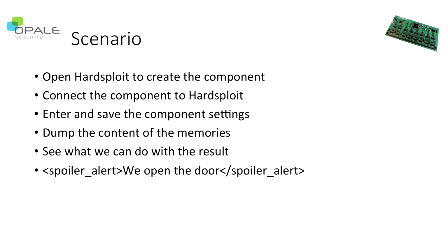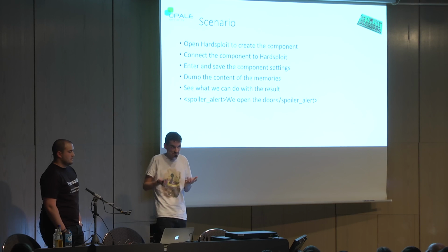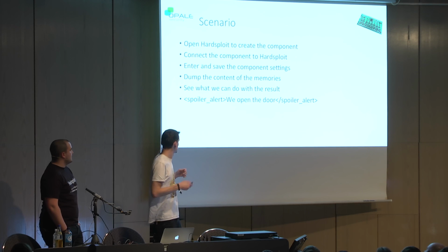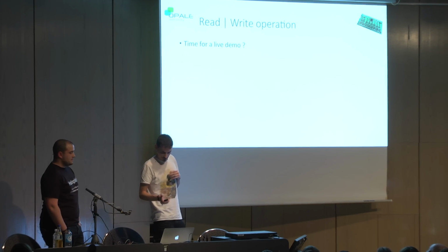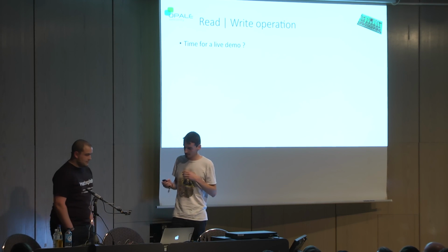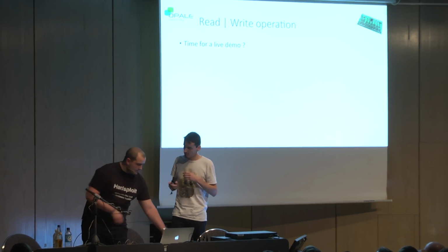And that's the scenario. We open Hardsploit, we create the component, we connect the component to Hardsploit, we enter the component settings, of course, and then we dump the firmware, the content of the memories, and we will see what we can do with that. Okay, so first, we are going to work with the I2C bus.